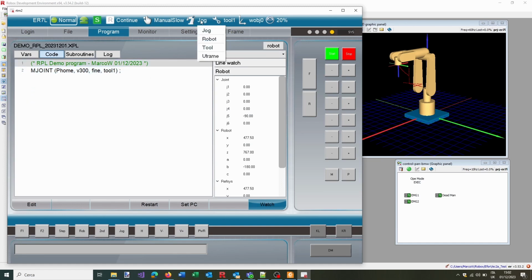Now let's move the robot. I click, I go in Cartesian movement. Let's go in minus z, for example, and let's go, for example, in plus y of some value. Normally, while you play with this kind of motion, you would like to do some pick and place or painting or welding application, and so normally you would like to teach points.